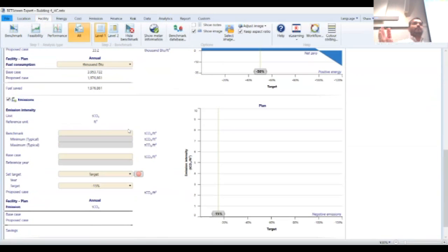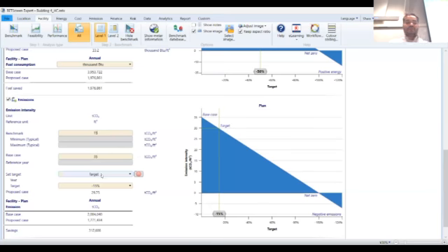For BEPS compliance, there are a few jurisdictions that require you to meet an emission requirement. So this is a place where you can see whether your property is compliant with the emissions target or not. You need to have the benchmark, which you get from the jurisdiction. For the base case, depending upon the total energy usage, you can estimate the carbon emission and plot a graph to understand whether you are meeting that requirement. Just an example, suppose right now you are at 35 and this requires 50, so you can understand from the emissions perspective whether it is complying with BEPS.